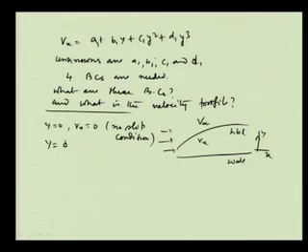At y is equal to delta, this is when it is reaching the boundary layer, so it is delta. At y is equal to delta, V x is equal to V infinity, that is the free stream velocity. Then that is happening for any value of x. And then at y is equal to delta, again, we have already seen that shear stress at this point we are assuming to be 0.